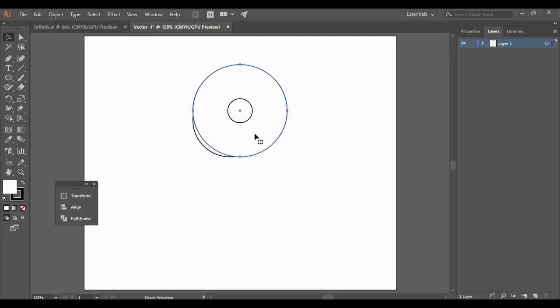Now I'm going to rearrange this circle. Okay, after the rearrangement, this is the kind of position for this circle that we wanted, and this is exactly what you need to do. You have to press the shift key and change its dimensions and then rearrange it so that it intersects with this smaller circle over here and with this larger circle over here. Then select the circle, press Ctrl+C to copy it and Ctrl+Shift+V to paste it in place, and just change its position to here.